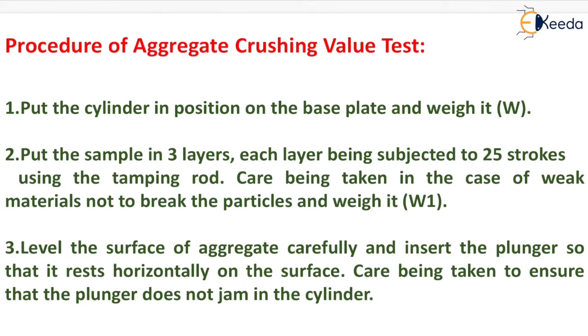It means that we have to take care during the tamping that the material does not break, and let the weight of the sample be W1. Level the surface of aggregate carefully and insert the plunger so that it rests horizontally on the surface. Care being taken to ensure that the plunger does not jam in the cylinder.